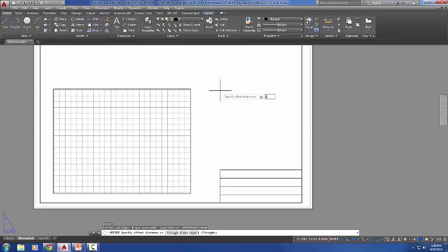I'm sorry, I said that wrong. 1.75. There we go. Select the object to offset. I'm going to take this line and bring it over 1.75, and then offset it 0.15. Actually, 1.5. I am so sorry, I'm saying that wrong. 1.5. Follow the book. It says the distances in the book for you, if I'm confusing you here.